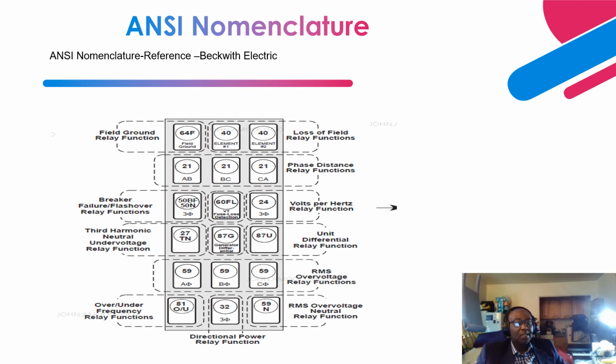With this relay, let's say there's a breaker failure: a relay sets an output and it's supposed to trip the unit breaker, and it fails, right? Then after a period of time, this relay senses that there's still current flowing through the breaker, and from there it starts a timer to trip other breakers that are in close proximity to the unit breaker that was supposed to be tripped.